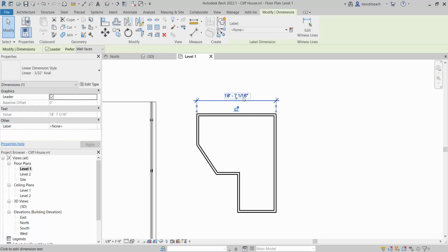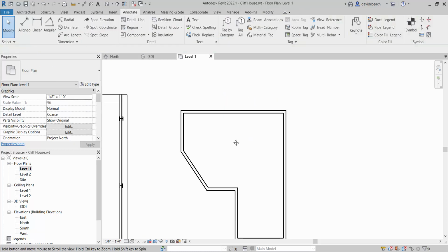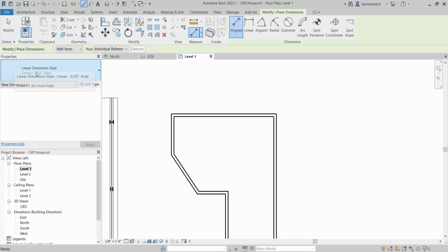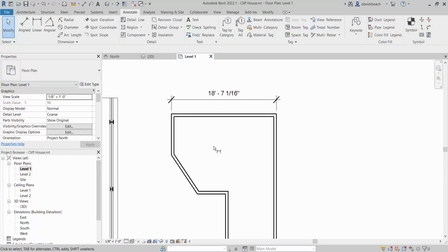Okay, so you should have on your screen, go ahead and drop in a series of walls. Then you're going to go to annotate an aligned dimension, change how you're placing the dimension to wall faces, and then you're going to run outside edge to outside edge. I want to get everybody to that point. And then I want to talk just really briefly, conceptually, why those are important standards that we use here regionally.